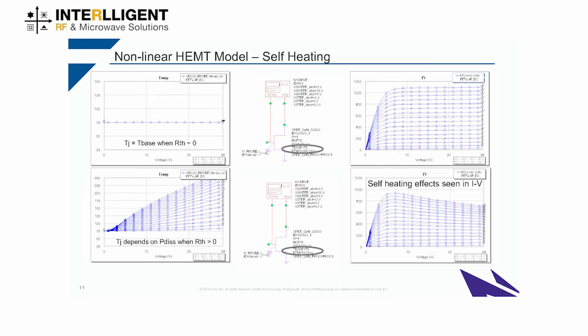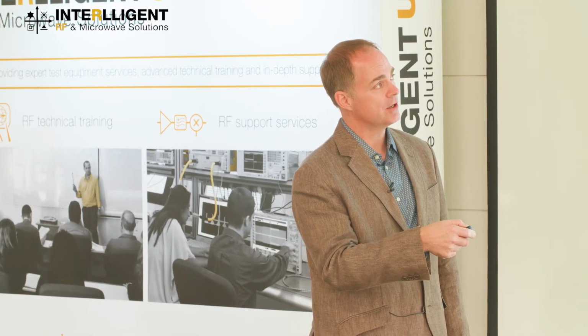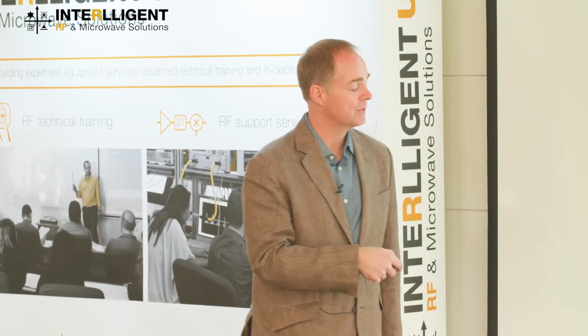So here I've just got a few plots of the thermal self-heating aspects of the device model. You can see in these top models, we've actually set the thermal resistance of the device to 0. So it perfectly conducts all the heat out of it. And you can see no matter what range of biases you apply to it and how much power you're actually dissipating, you don't actually see any rise in the junction temperature. It's at 75 degrees C across the way. While over here, you can see that there's no droop in the IV curve as we run these through the bias range.